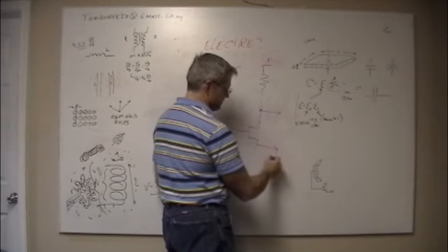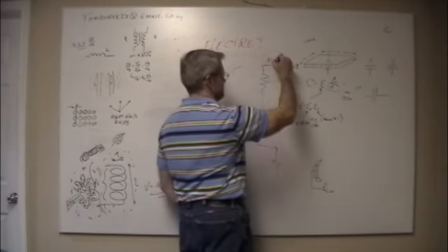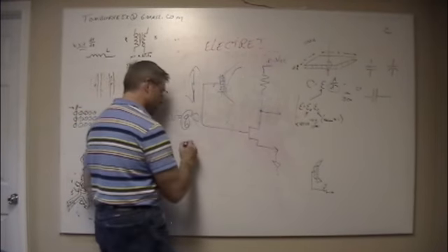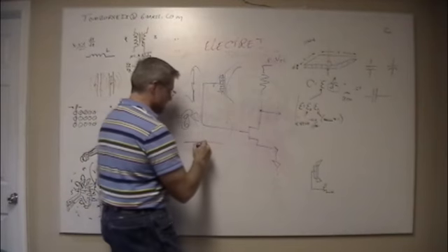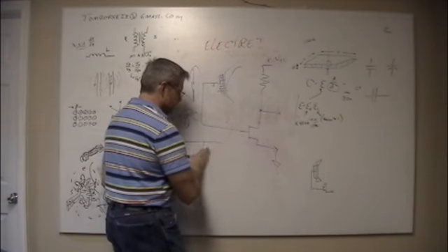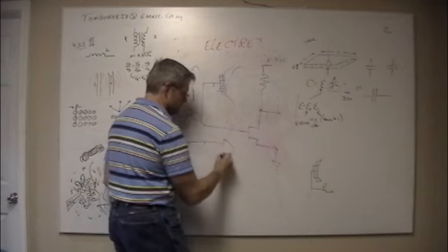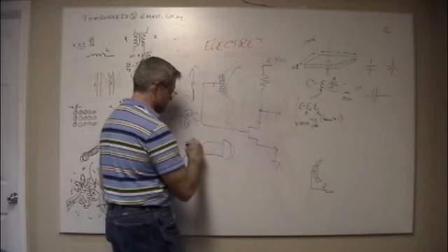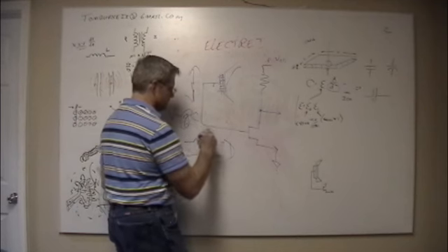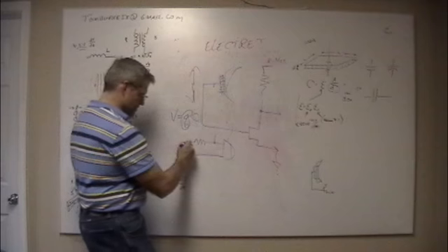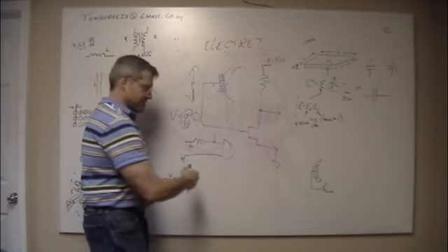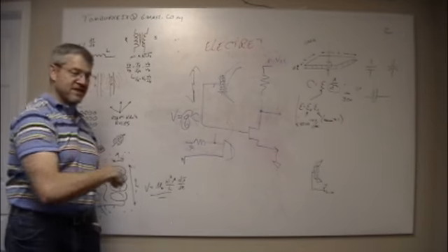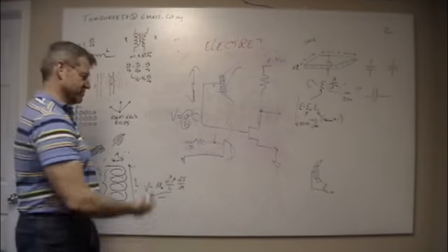But you basically tie this to ground, so this is your ground, and this is VCC, your power. And now what you're doing is you've got your power rail out here that you're powering everything else off of, and it comes in and hits this Electret mic and goes to ground. So the way you pull your signal is you put a resistor here and you pull your signal right there. And you want to have a good capacitor here, otherwise you're injecting whatever's on this back into your power supply. If you've got a really stiff power supply, that doesn't matter, but if it's just a half-assed power supply, that can be a problem.